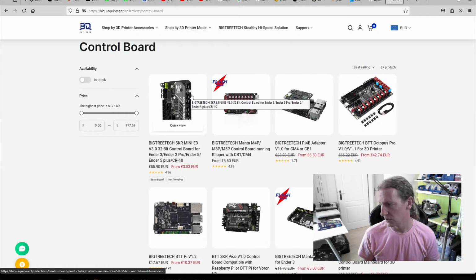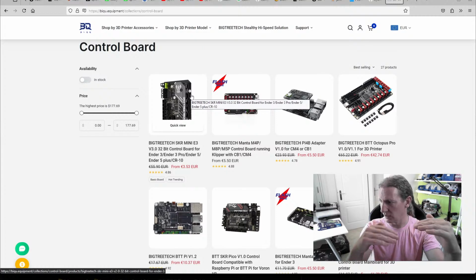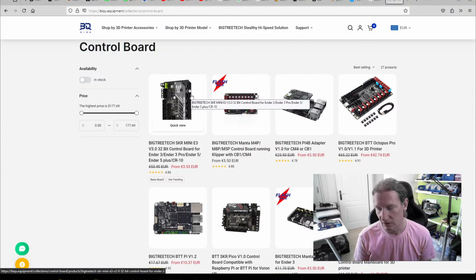Other machines have a cam arrangement where they have a single head which has a single stepper motor, and if it turns in one direction, it moves one nozzle down and the other nozzle up. And then if it turns in the opposite direction, it moves the other nozzle down and the first nozzle back up again. But they're on a cam, so they never go too high. And there are lots of examples of machines like that.